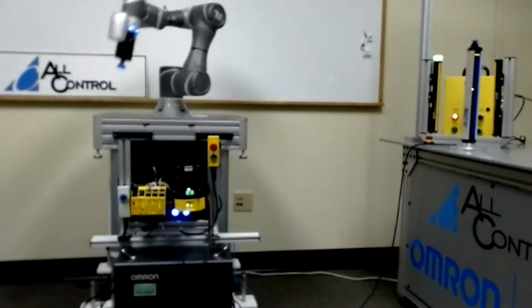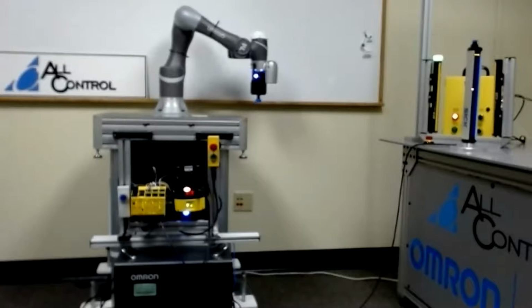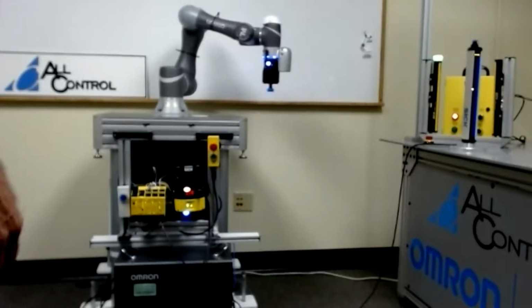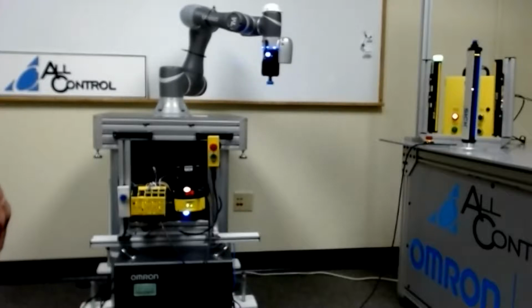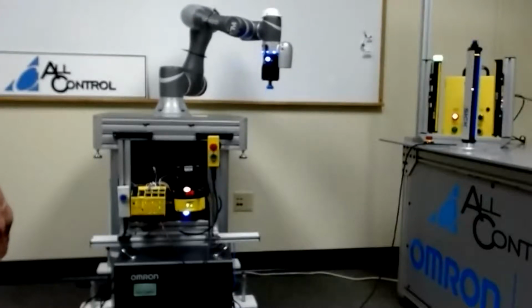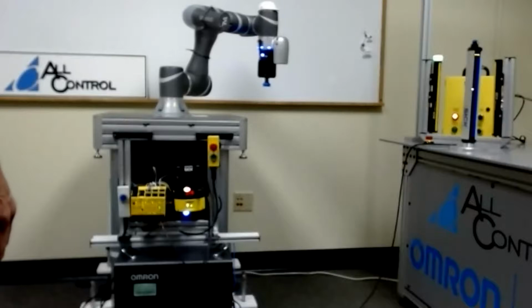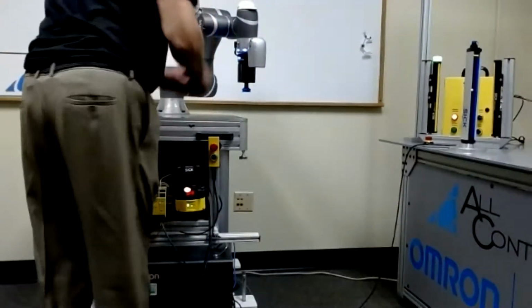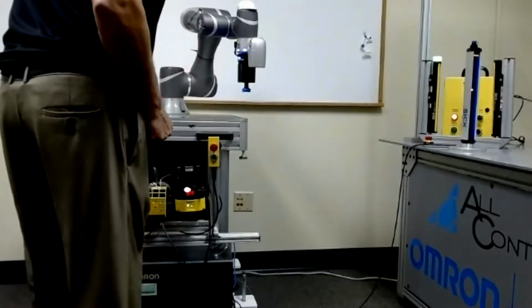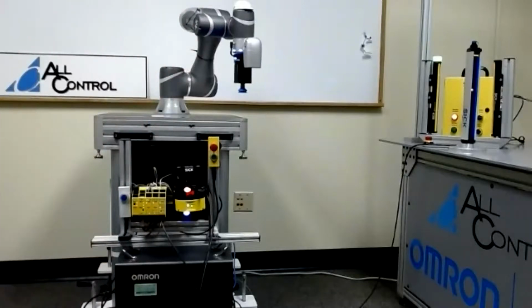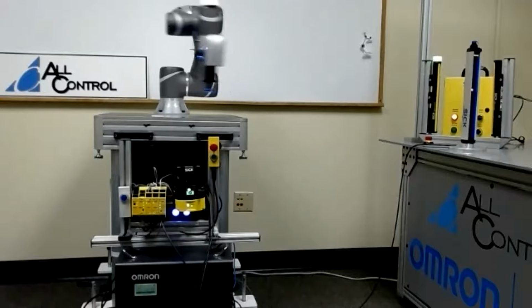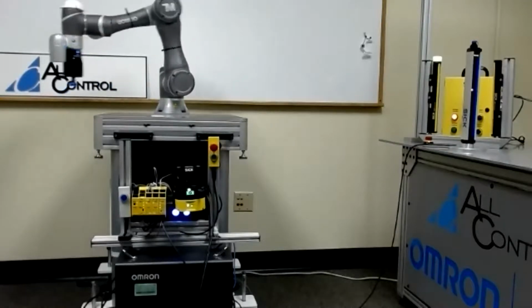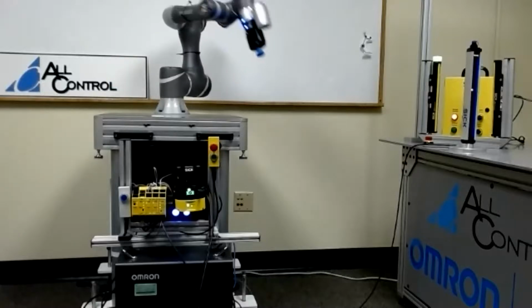So when the robot's running full speed, when we start to enter the area, you'll notice the robot is going very slow. That's collaborative speed. Can't get much done in that speed, but at least it's getting something done, and I can work around the area. Then as soon as I go to work with the robot, take my work piece away. As long as I've continued the sequence, the robot will start working again. That's the basic concept of the speed.